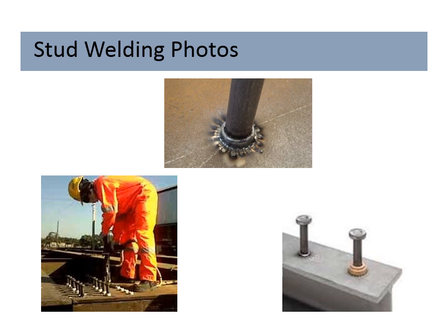Here are some stud welds. In the top picture, you can see what the weld looks like after the stud has been made. This is a high production process, by the way, if I didn't mention it. You can set up and do hundreds of these welds pretty quickly. Whereas if you had to weld these all by hand, it would take you a significant amount of time to make all of those welds.